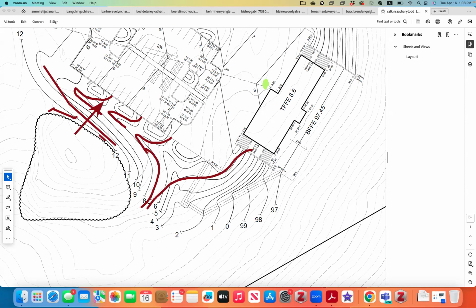If you want to, you can have one more little retention here to receive some water from the swale here. You don't necessarily have to. If you just wanted to flow this way down, spread into a sheet flow manner, then starting from the 6th contour, I will get rid of the swale signature and basically do something like this.